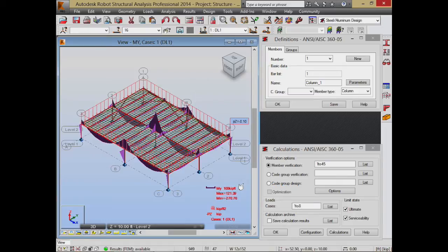We're going to think about the different elements of the structure and put them into different categories that belong together. So for example, the columns might all go together. I could say that the exterior columns are different from the interior columns. That might be useful categories. When I start thinking about the beams, the exterior edge beams are probably different than these two beams in here, the interior beams, because they're double loaded versus those only being single loaded. So I might put those four together and those two together. And all these front to back beams are actually pretty similar in the scheme of things. They don't really change a whole lot given the way this is designed. And braces, again, are their own separate thing.